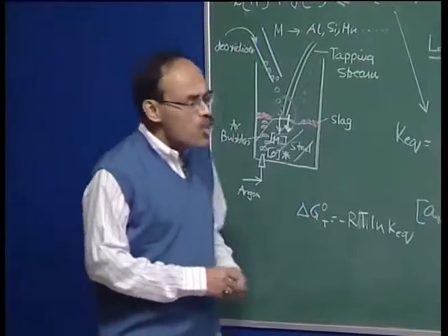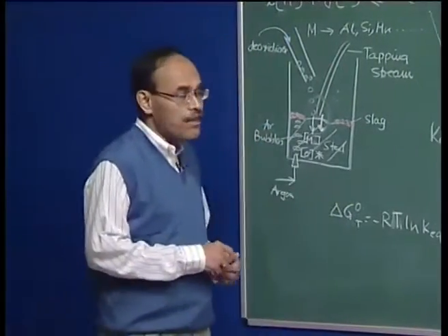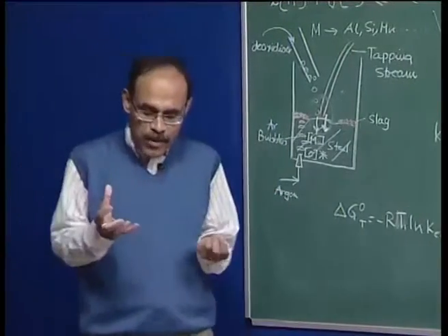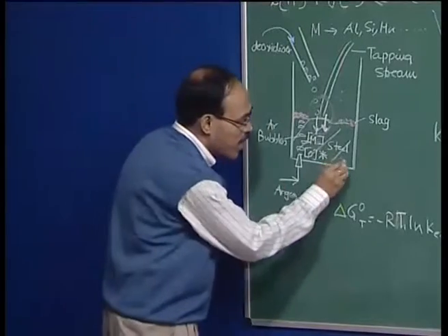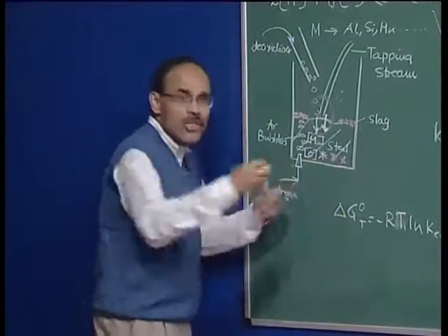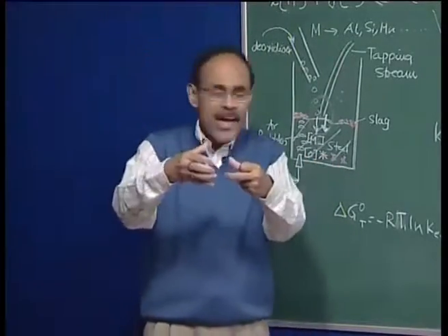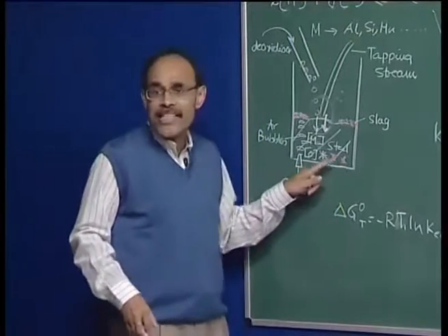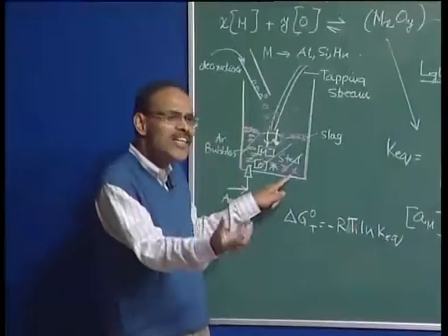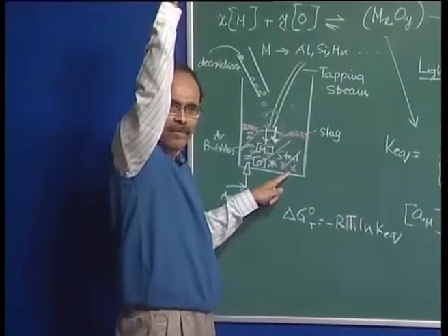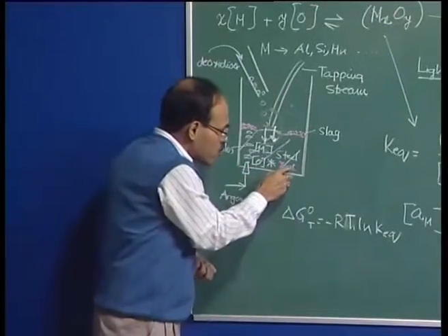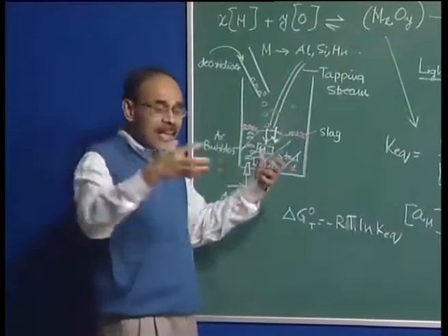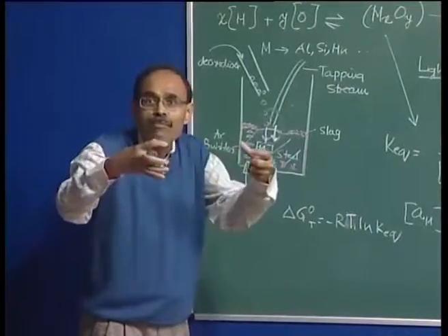So, if you have solid deoxidation products, one solid deoxidation product can form here, the other can form here, but the solids do not collide. And these deoxidation products are basically lighter particles, so they naturally have a tendency to float up to the melt. But one important thing is that these deoxidation products, if they are solids, do not tend to form bigger masses.